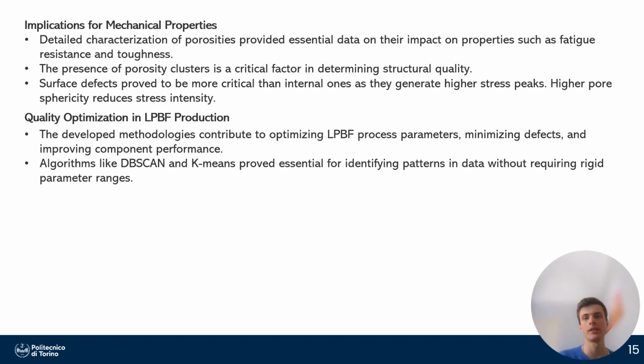The detailed characterization of the pores has also provided crucial insight into their impact on mechanical properties such as fatigue resistance. Indeed, porosity clusters play a critical role in determining the structural integrity of a component. Among the defects analyzed, surface defects were found to be more detrimental than internal ones, as they induce higher stress concentration. Additionally, it was observed that higher pore sphericity led to lower stress intensity compared to irregular porosity.